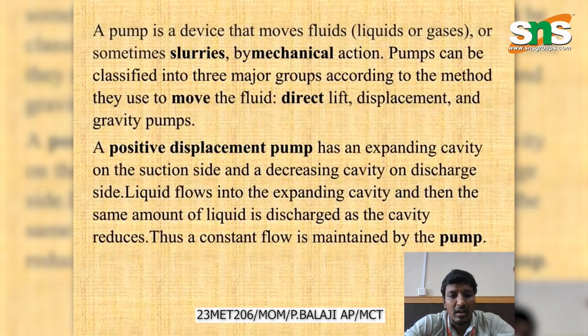The principle: the suction side creates an expanding cavity and fluid enters the cavity. On the discharge side, the cavity volume decreases and the trapped fluid is pushed out under pressure. This ensures a nearly constant flow rate.